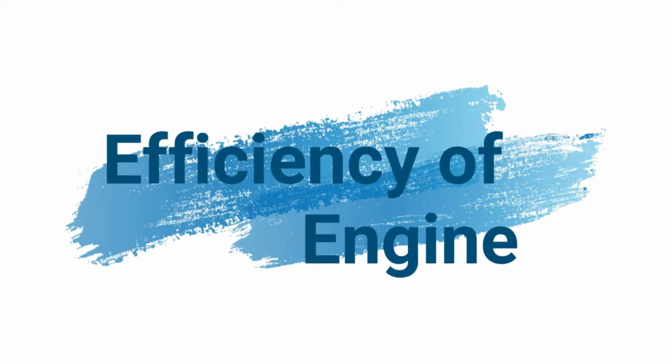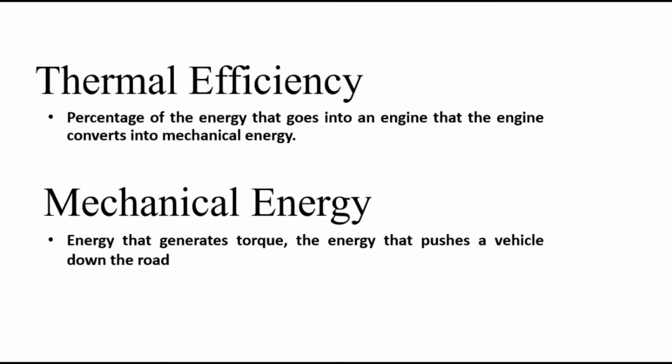The efficiency of an engine depends on its thermal efficiency. Thermal efficiency is the percentage of the energy that goes into an engine that the engine converts into mechanical energy. Mechanical energy is the energy that generates torque, the energy that pushes a vehicle down the road. The greater the compression ratio of an engine, the greater the thermal efficiency, meaning the higher the percentage of the total energy fed into the engine which becomes power, as opposed to being lost.